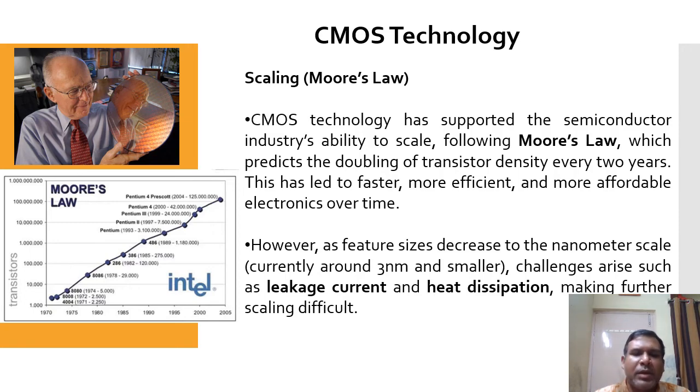It will continuously shrink the dimension of the MOSFET, and what are the challenges? The main challenges are that it will generate more leakage current, heat dissipation is very high, and it makes further scaling difficult. Below 3 nanometer technology, this Moore's law will not work.